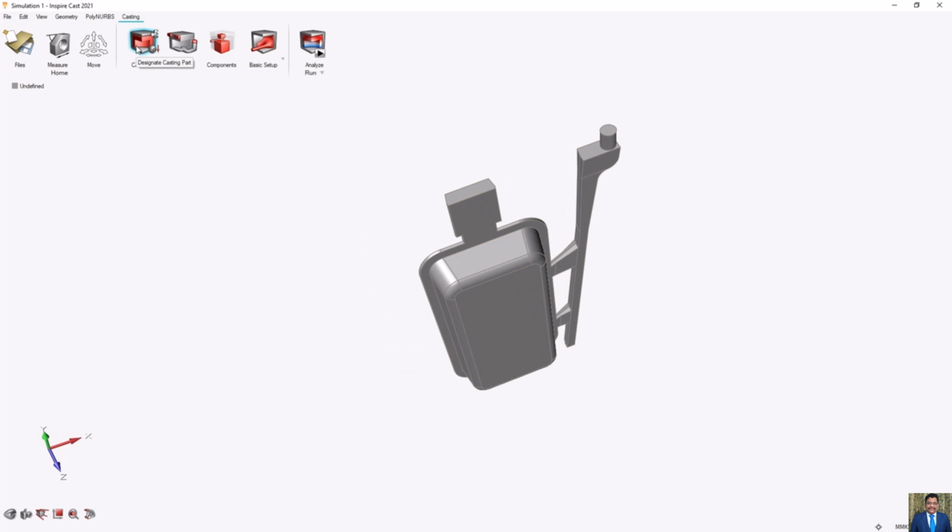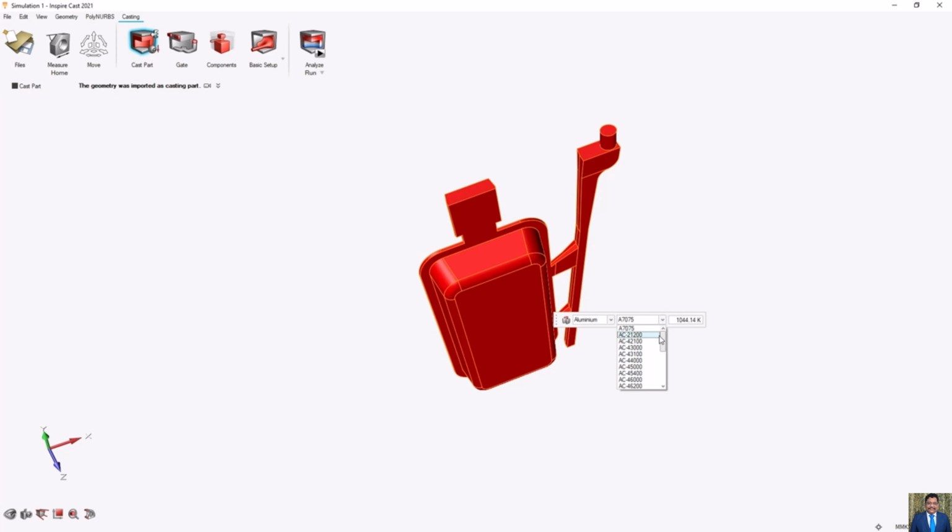And here it's to define the material, which material we want to use for casting, and we have it here. We have aluminum, and different materials here, but I want to use 44100 here. And here is the temperature for casting aluminum, but it's like a limit. It's better when you start between 670 and 780. It's between that temperature, it's good. But if we go with 740, we go in Celsius because we have Kelvin.